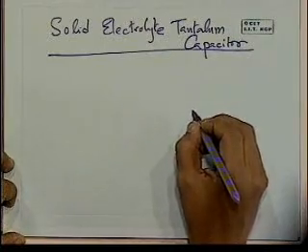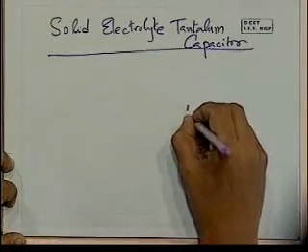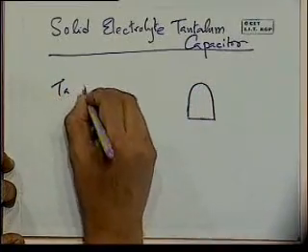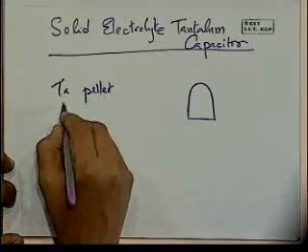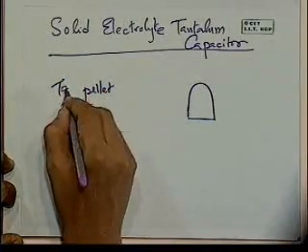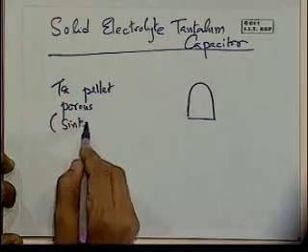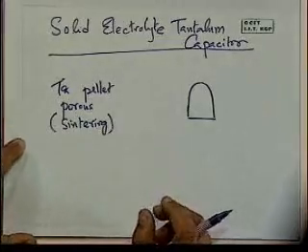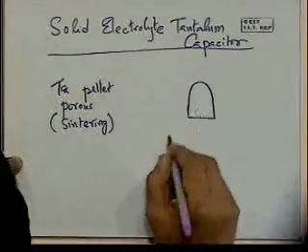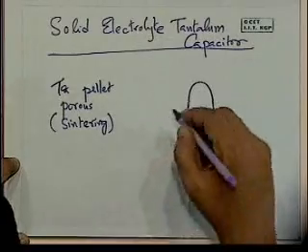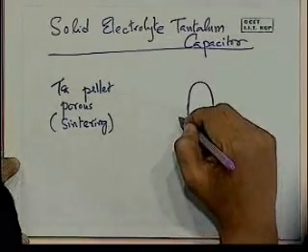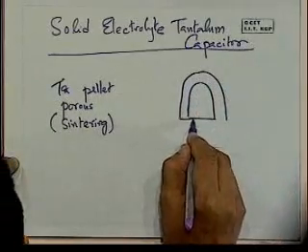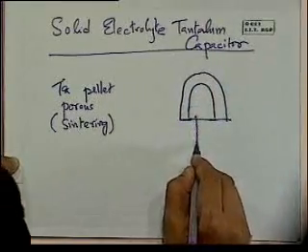Essentially, the anode consists, let me give a sketch of what this device will look like. There is a tantalum pellet, which is porous. And it is created by a process called sintering, compacting it and keeping it at a very high temperature where it will densify. So that's the tantalum pellet. And then we have around it, I'll show the cross section in a second. Let me just draw this. There's silver paint, and then some leads that come out of it.